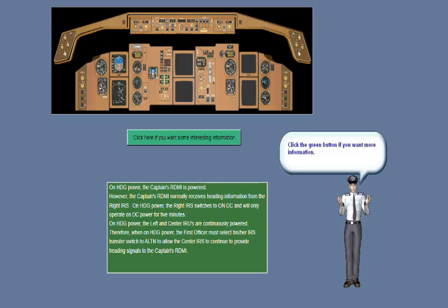How do you know when the HDG is activated? You would see the indicators of a dual AC bus failure, with the exception of the items that are powered by the HDG-powered buses. The immediate indications of a dual AC bus failure are a blank first officer's ADI and HSI display, blank ICAS displays, and an activated standby engine indicator.